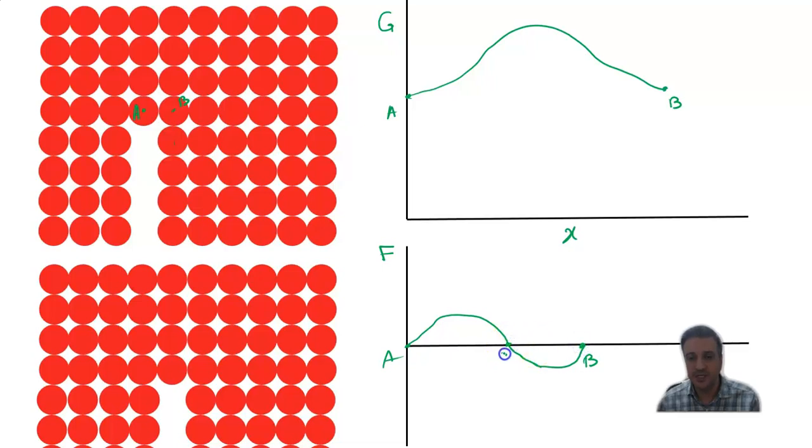The position that you see here is named position C. It is a very unstable position for the dislocation, because as you can see here, we have a maximum in the energy of the dislocation, and in this maximum the amount of the load exerted on the dislocation is 0, but it is very unstable, and it finally changes its position to the more stable position, which is B.